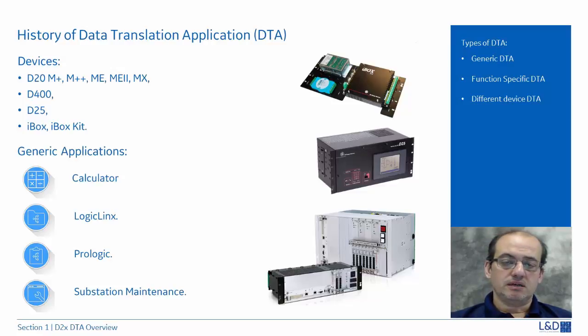There are many applications that serve the generic need, and there are applications, like we said, that serve the specific need. For example, there is also the substation maintenance application, which means that you turn this on, and then no alarms will be transmitted to your operators while maintenance is taking place. So you don't want false alarms at your operators.